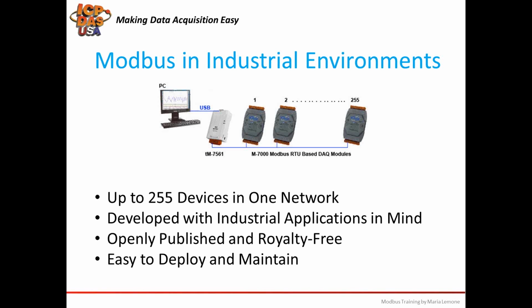And if you want a cabled application, the Modbus RTU can go up to 4,000 feet without a repeater or switch, so that communication distance is longer. Otherwise, if you want to go really long, you could use a serial to fiber switch. We provide those, or Ethernet to fiber, and then you can tap into the fiber cable, which can go a lot greater length.